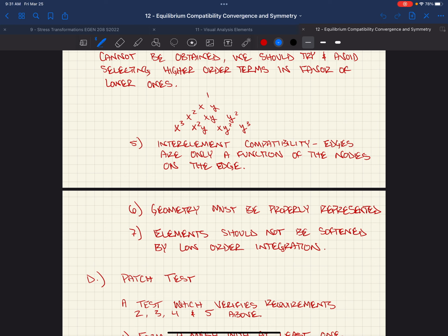And then you weight the sum of those to get the real answer, right? And so if you do, say, 2 points of integration, obviously you're only gonna calculate 2 points of actual value within that integral. And then if you sum those weightedly and say that's your answer, that's gonna be not as accurate as doing something like 10,000 integration points, right?